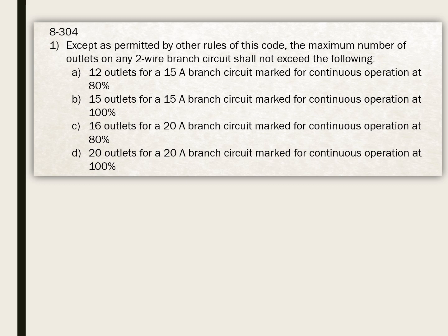Typically, we're going to be using 80% rated breakers, which are typical for housing. Therefore, we can have a maximum of 12 devices on a 15 amp circuit and a maximum of 16 devices on a 20 amp circuit.